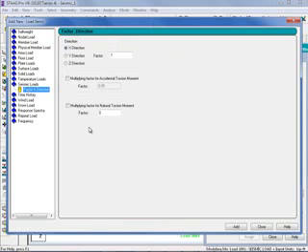And here I have a variety of options available. This load case represents seismic load in my X direction, and I'm going to keep the factor set to +1, which indicates in the positive direction. I'm also going to select my multiplying factor for accidental torsional moment checkbox, and for the accidental torsion to be considered, it is necessary that the seismic load definition also includes that checkbox for accidental torsional moment.